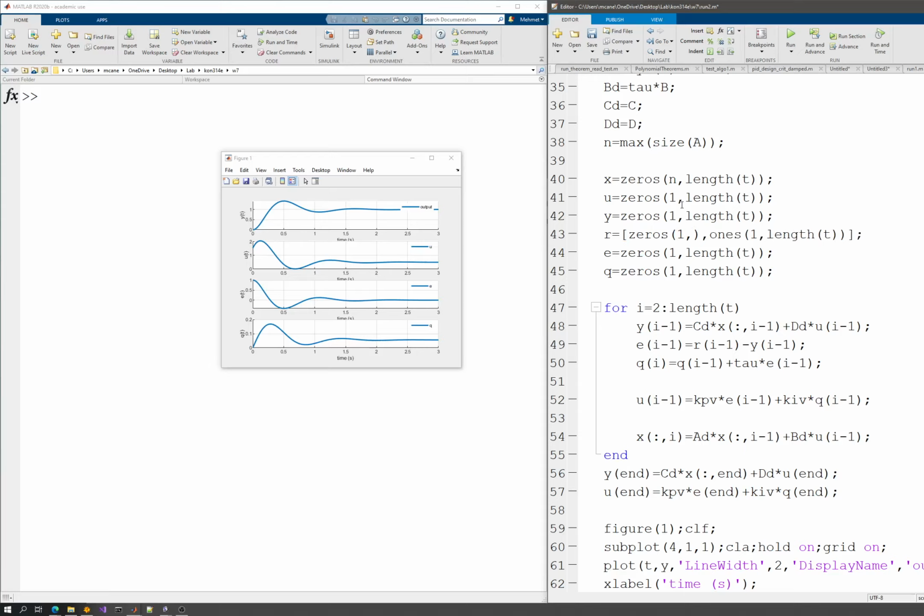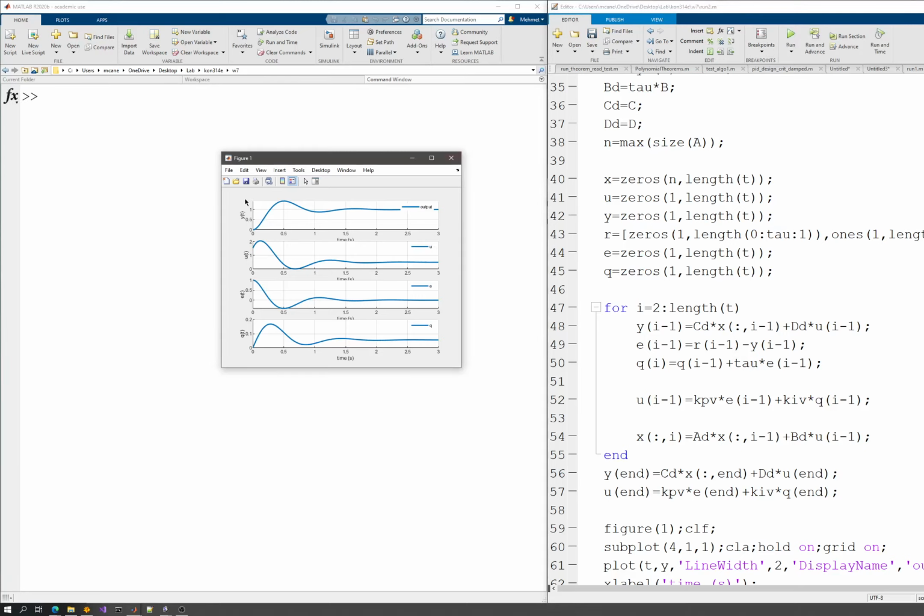Now, the size of my first part should start with 0, and it will have this sampling, or did I have tau? I have tau, so this is a better idea. And the ending point is 1 second, so basically I will have a 0 vector that starts at 0 and will stop at 1 second, and I will then start with 1, I will have an increment of tau, and my last value will be the same as the time instant here. So I have to add 1 plus tau because this is the last sample and the next sample starts at 1.01, so I should add a tau in order to have the same size as the other ones. If a size mismatch happens, then you will get an error.